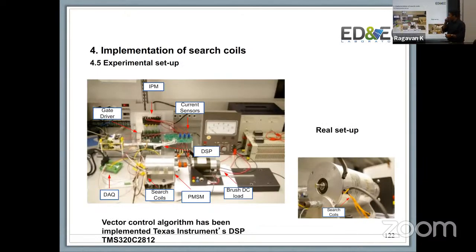So this is the actual setup here. We had the DSP controller connected, that's in the back. We had a Fuji gate drivers based converter setup here. We had the switch module, the inverter module. Surge coils were connected, and then we added a data acquisition card by MathWorks. So it was a MATLAB DAC card from them. All we did was plug those numbers into our DAC card. The reason for that was because it just made it easier. You can replace that with a microcontroller, or any other system that can gather the information.